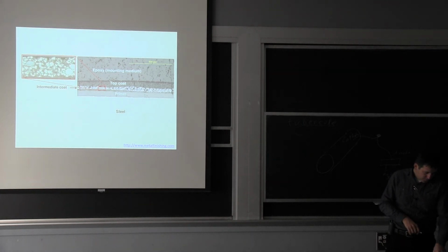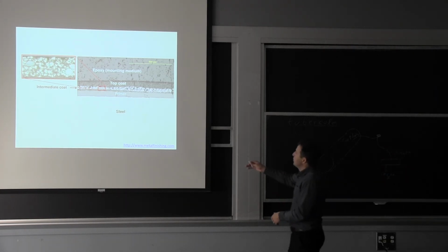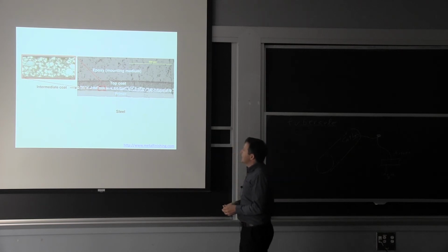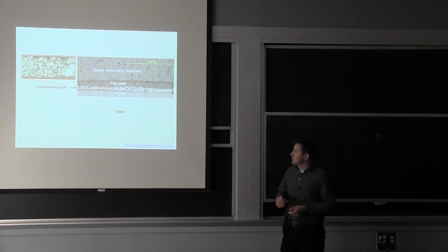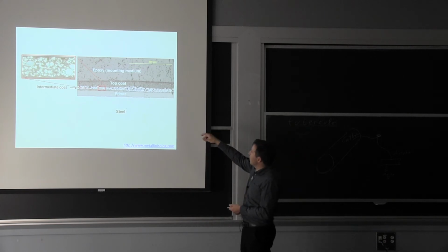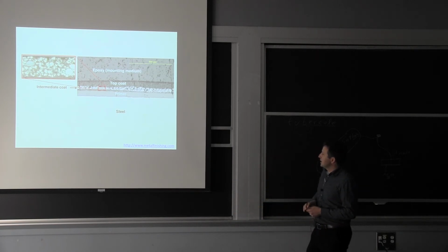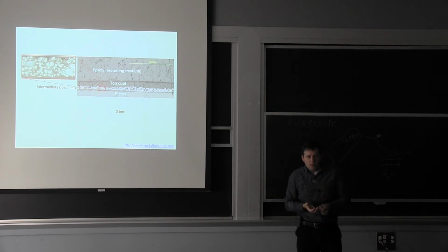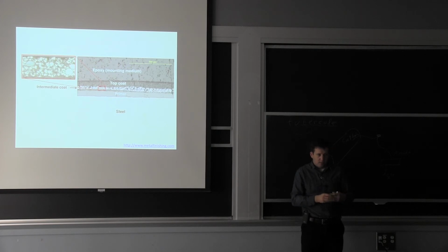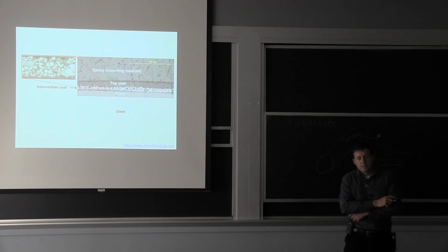What's very common with the organic coating is to have a number of coats. And the idea there is to create that adhesion. So if you're looking here, you have the steel, you have a primer, and you have your top coat. And then the top layer is just a mounting material. But the idea there is you need adhesion. So you need kind of a sponge effect, something that will just absorb whatever is in there to begin with, and then you put your hard layer on the outside to make sure you don't get anything to penetrate on the inside. Yes? What's the function of the primer?